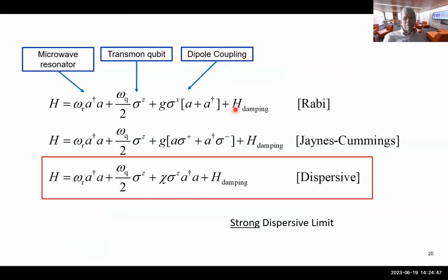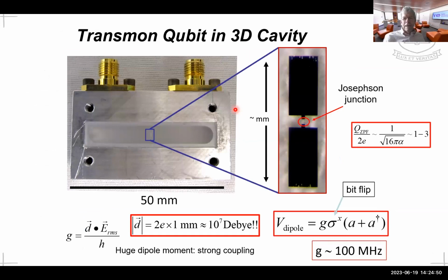Oh, in the transmon, the capacitance is just the geometric capacitance between these two antenna pads. There's also capacitance from here to nearby walls in the resonator and stuff like that. There's also a little bit of capacitance in that tiny Josephson junction. It doesn't have much area, but the capacitor plates are only a couple nanometers apart. So it actually contributes about, what, Michael, 10% of the total. I think even less, yeah. Usually we just leave it off because it matters so little.